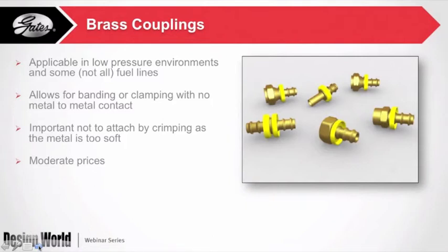So you can put these on up to about 300 psi of pressure. No clamps are required. The clamps will actually cut the tube of the hose because of the sharp serrations in the brass. So we don't recommend clamping unless you've checked with the manufacturer of the coupling to ensure that clamp's not going to cut the tube of the hose that it attaches to.